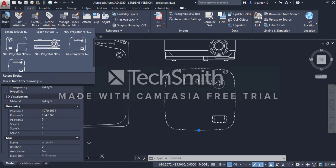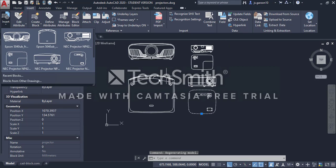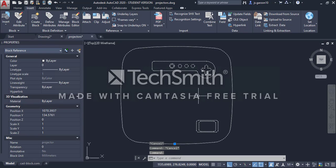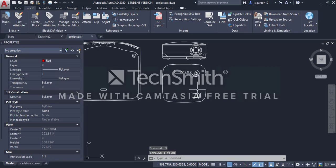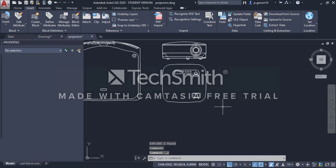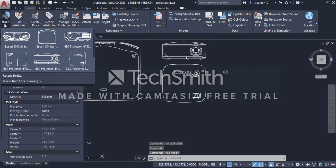All of these blocks were previously created, but if, for example, you don't want to have the object as a block, you can simply type X to explode it, and it will be back to lines again. So that is the advantage of managing blocks.